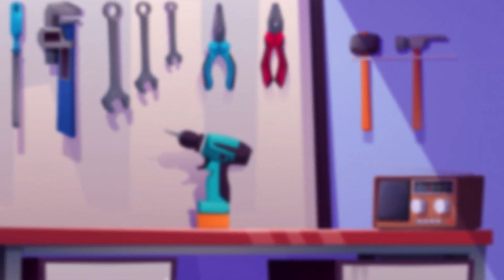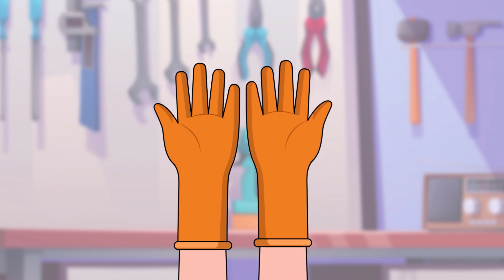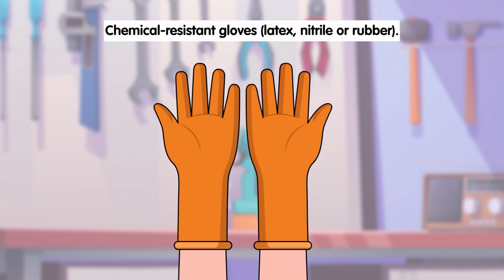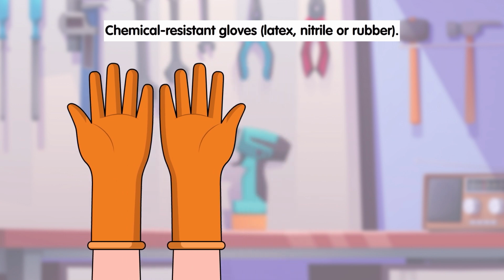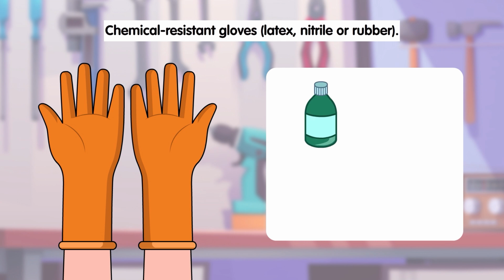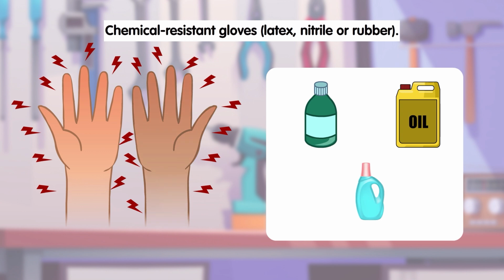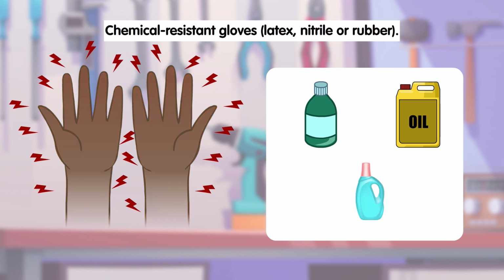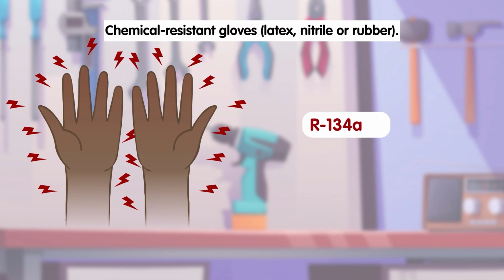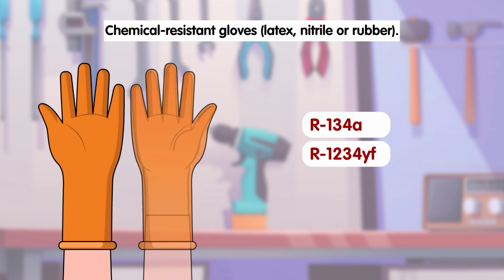The required protective equipment: gloves. Type: chemical resistant gloves, latex, nitrile, or rubber. Purpose: to protect your hands from coming into contact with refrigerants, oils, and other chemicals that can irritate the skin or cause burns. Refrigerants such as R134A or R1234YF can be particularly harmful on direct contact.